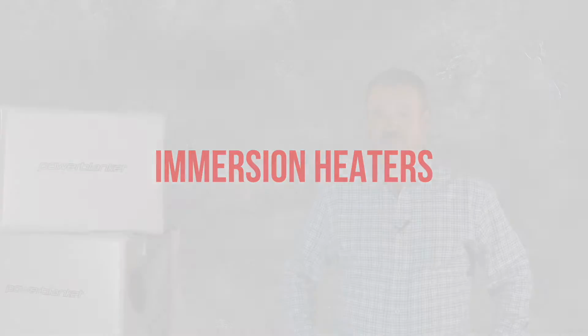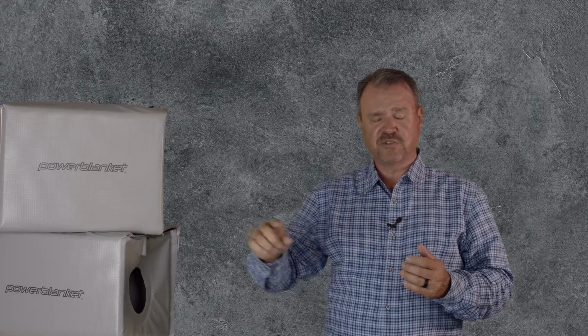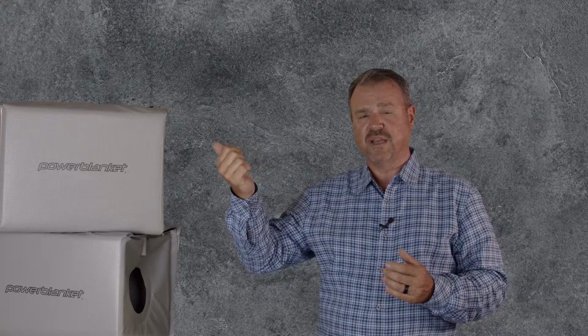There just aren't many industrial facilities that don't employ some form of electric process heaters. They can be used to heat lube oils. They can be used to heat gas streams. They can be used to keep tanks warm. There's just dozens of applications. A circulation heater, for example, can be used to heat a fuel gas stream going to a turbine. One of the most important things in a turbine is not have any water in the stream. When that gas travels through our circulation heater and goes to a fuel gas heater, it can knock out all of the water. They're actually called dew point heaters.